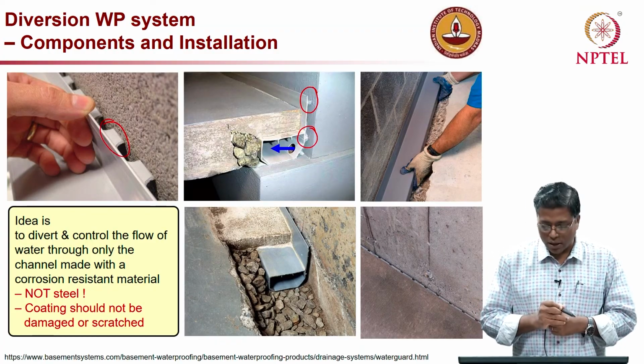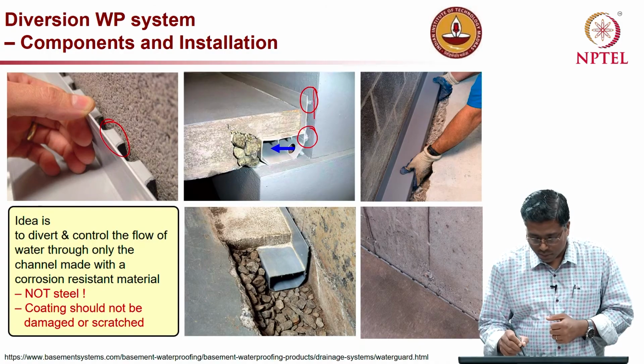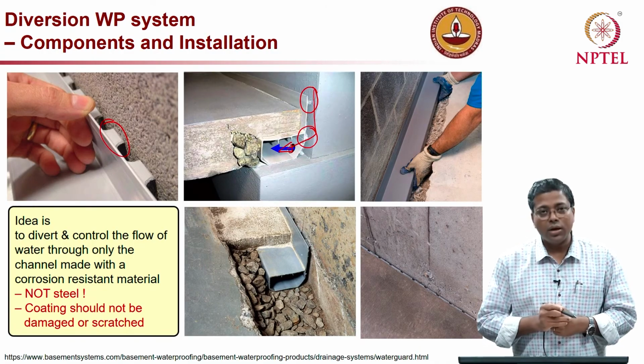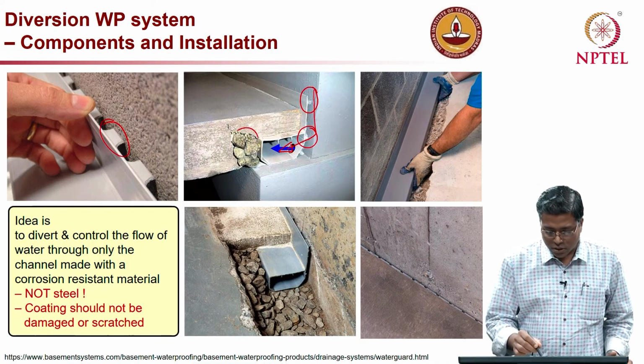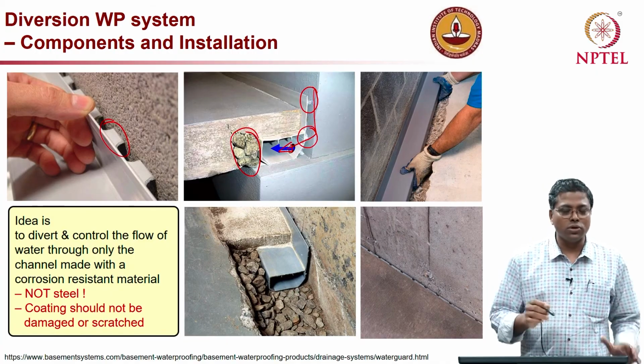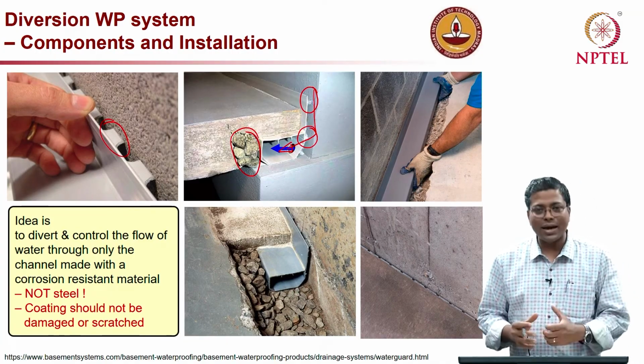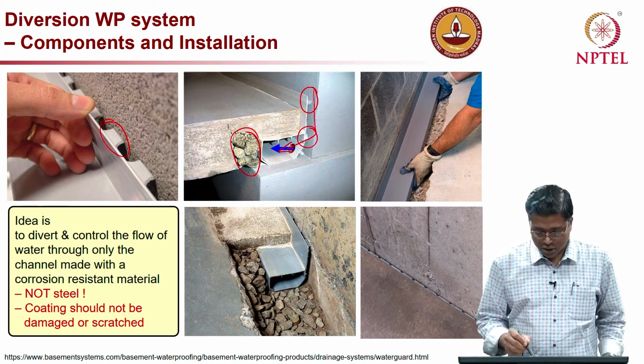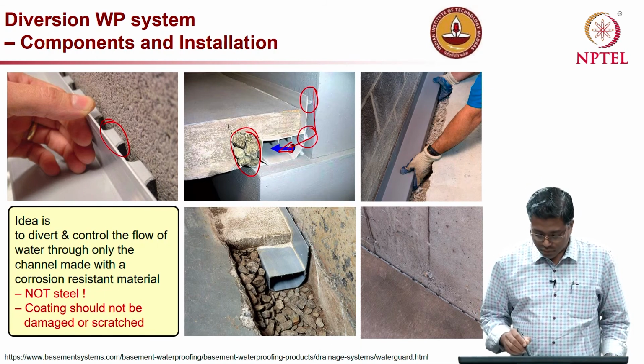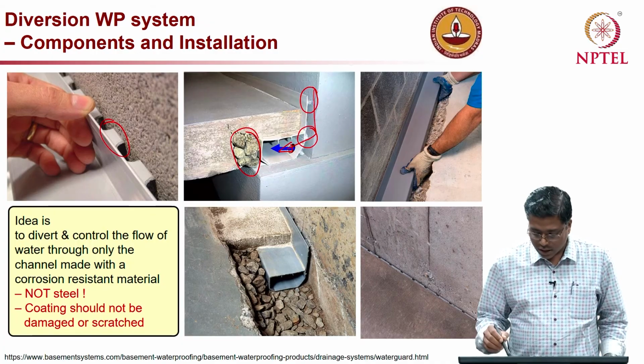The blue arrow over there is showing how the water is coming through and then getting into the French drain. And also this gravel is very important, because you want water from all around to be collected and then forced into the drain pipe, which we call French drain.